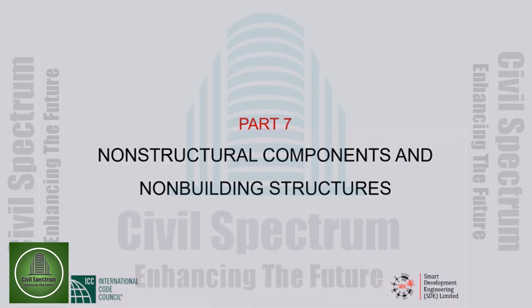So spectral displacement is the same as maximum displacement. Spectral velocity is actually spectral pseudo velocity because it is not equal to the maximum velocity of the system but very close to it. And the spectral acceleration is actually spectral pseudo acceleration because it is not the maximum acceleration of the system but something very close to it. In a certain period range, the structural response exhibits constant spectral acceleration.